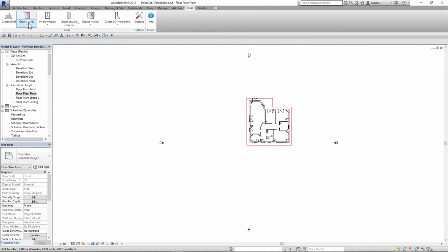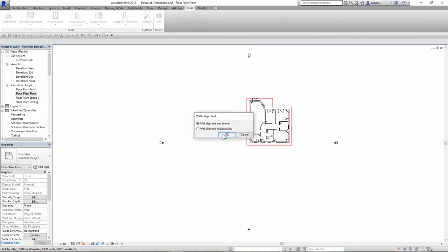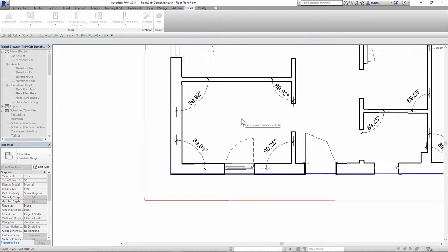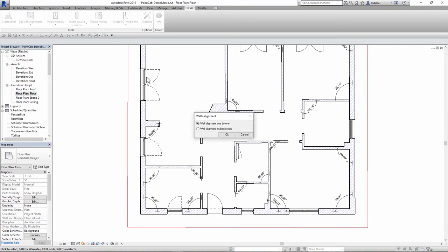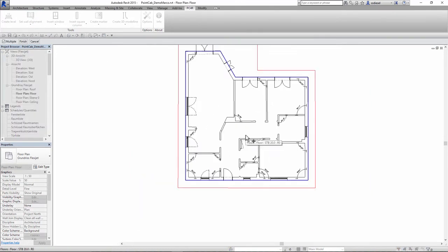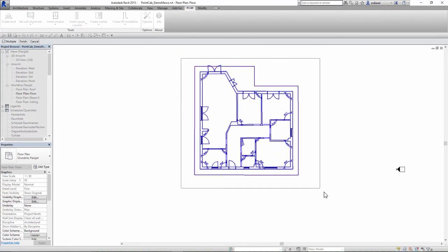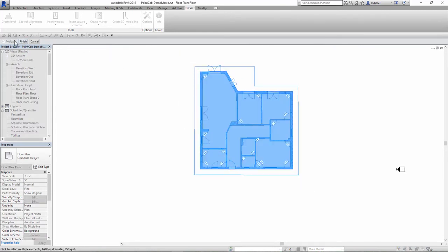We now select the wall function alignment and the method 1 by 1. We then simply click on the desired wall segments. With multi-selection, we can align an area and also the walls in one step. Here, too, the walls remain unchanged with an angle above the set tolerance.